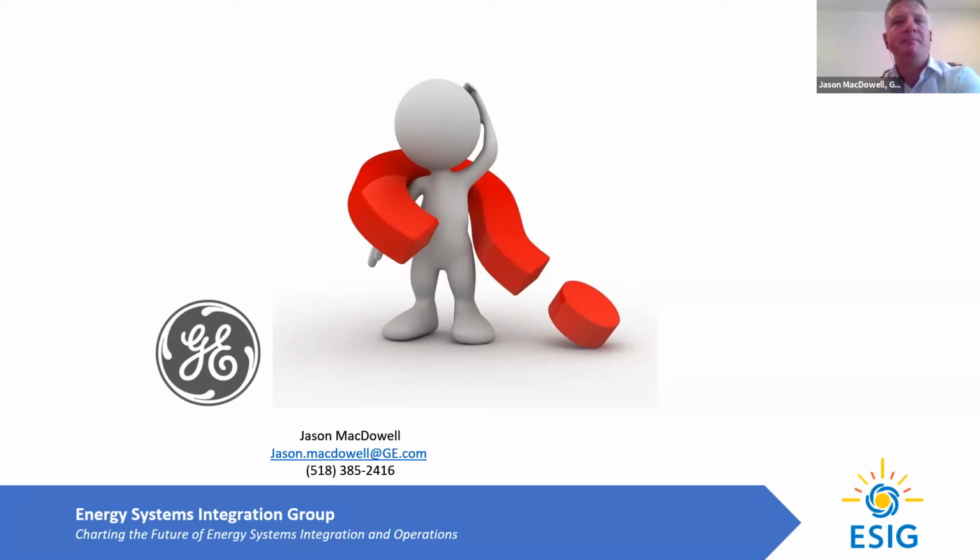Yeah, this is Nick again, throwing in a little color commentary. What Jason said, do make a distinction in your question. Flicker is largely an issue in the distribution system, very close to the load. Voltage variation on the bulk power system, that example that Jason showed that was work that he and I did 15 years ago, that voltage regulation is perfect. That's a non-issue.